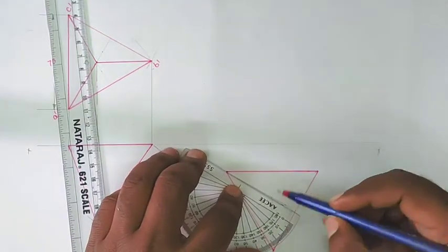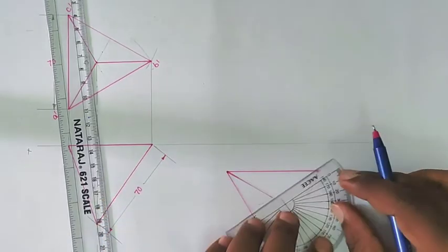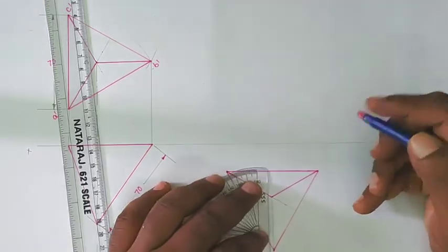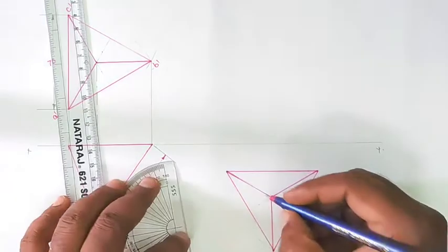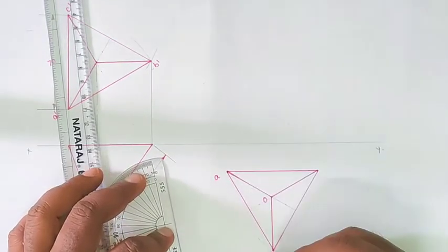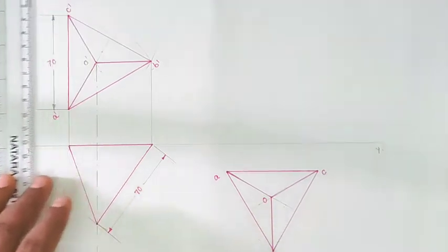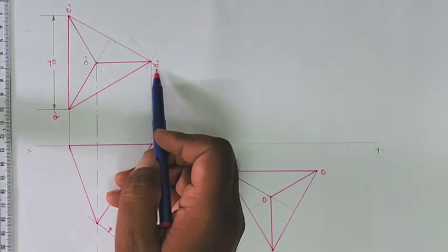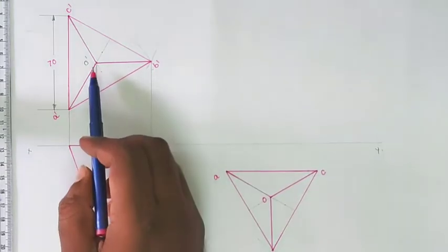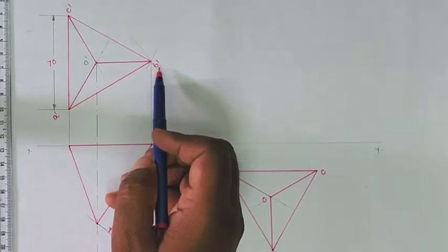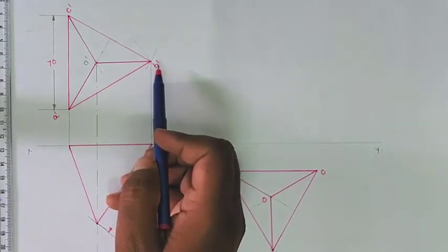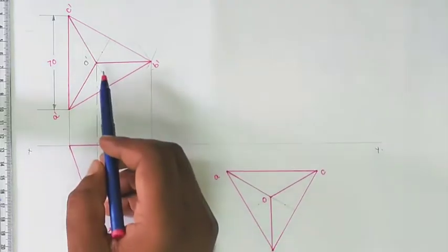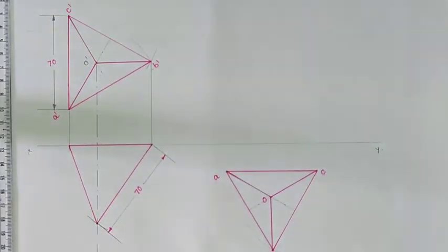So that this edge is also made thick. So this is O, this is A, this is point B and this is point C. If you observe here in the first problem, corner to any one of the sides you can take parallel. Whenever we draw the axis line, you can take corner to any one of the edges parallel to the reference line. Whenever it is parallel to the reference line, we will draw the projection up to the reference line, and with the length of the edge we will draw the axis line.